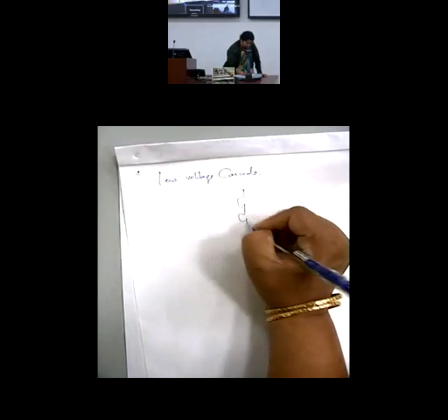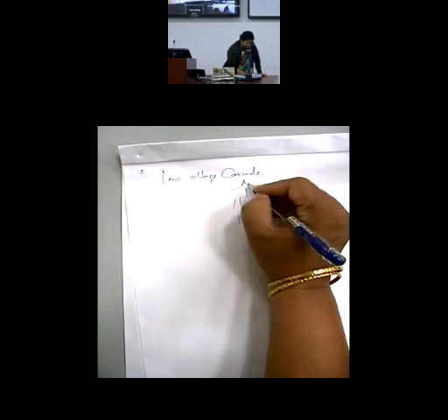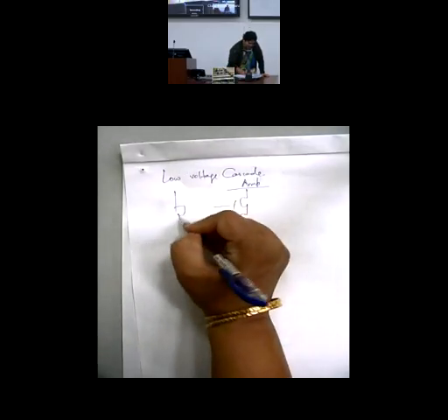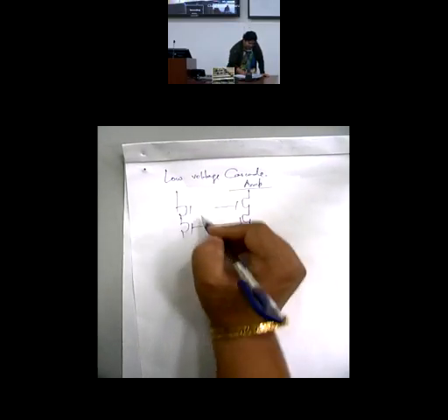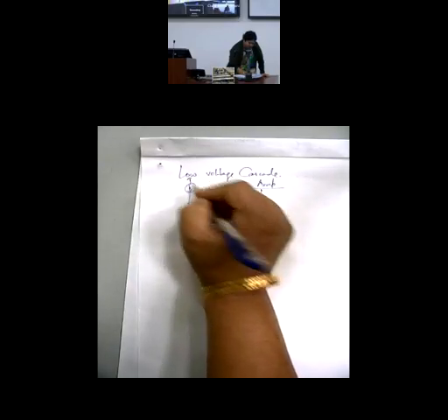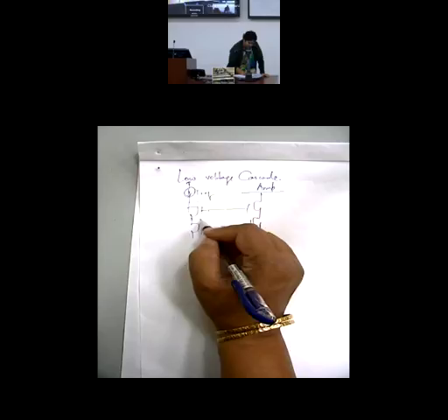So rather, I again have a look at this amplifier connection here, a cascode. In a normal situation, I make in the reference arm both transistors diode connected. Remember, I normally go for this connection.